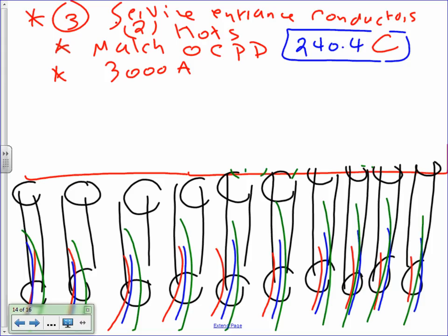Can I find a conductor that can carry 3,000 amp? I can't find one. So what do we do? Parallel. Everybody heard the word parallel? You can't parallel less than 1 aught, and you have to parallel your conductors. I decided to parallel 10 runs, 10 conductors.